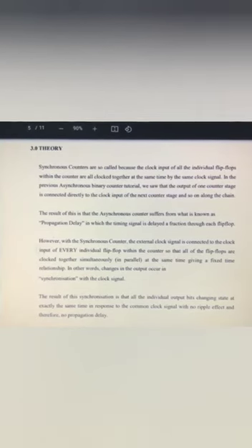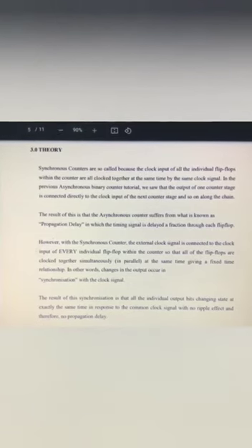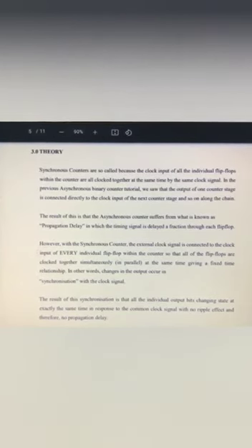In other words, changes in the output occur in synchronization with the clock signal. The result of the synchronization is that all the individual output bits change state at exactly the same time in response to the common clock signal, with no ripple effect and therefore no propagation delay.